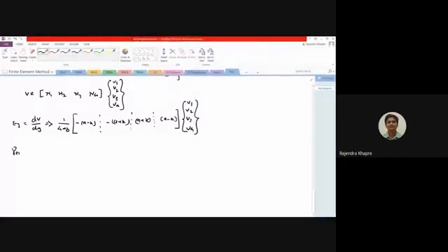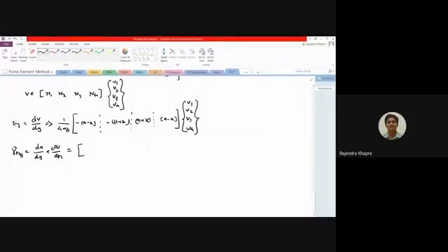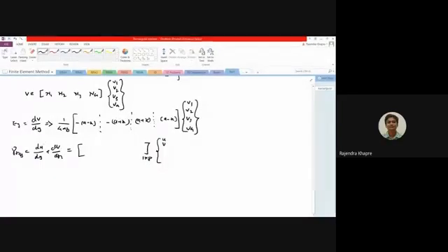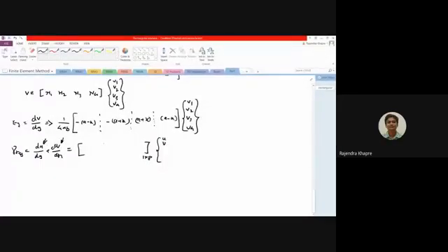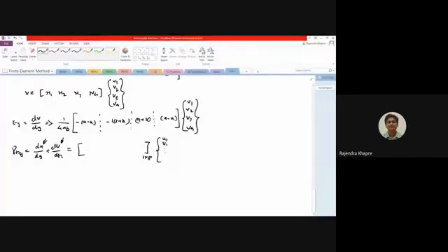On similar lines, we can also go for the shear strain. So shear strain, that is gamma xy, will be calculated as du by dy plus dv by dx. Here also you will get some different term. Here you will get one row and 8 columns, multiplied by the u term as well as the v term, because the u term is over here and the v term is also over here. So you will have something like u1 v1 and so on, up to u4 and v4.